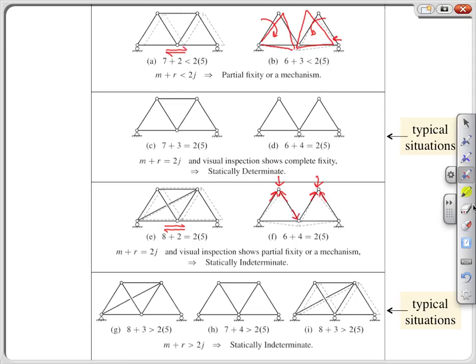So here are the compressive loads that are brought into this joint from the equal and opposite nature of the members that are required to support the vertical loads at the top. And then there has to be a change in geometry here at the bottom so that we get vertical components here able to counteract those compressive loads coming in from the top. So truss F can only be in equilibrium in this case after experiencing significant deformation.